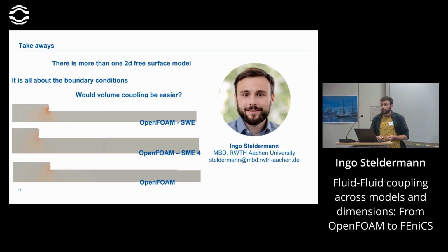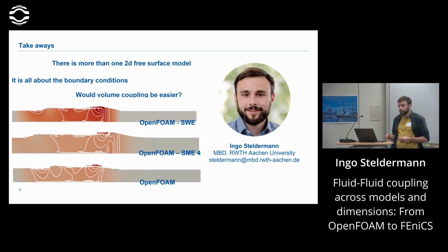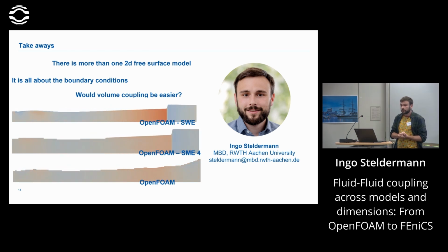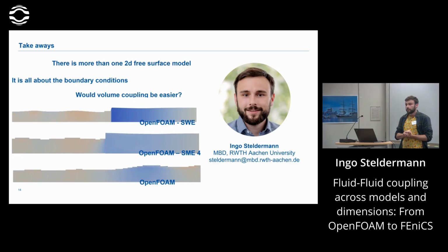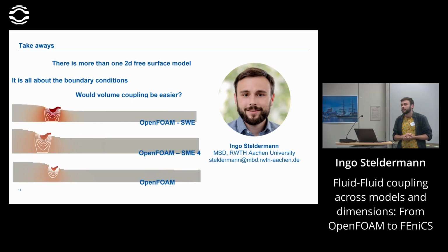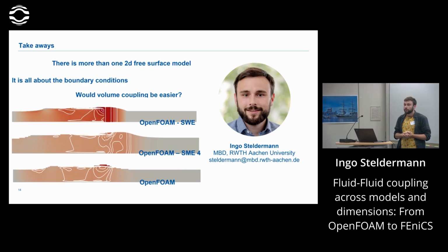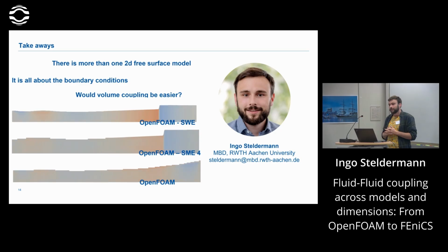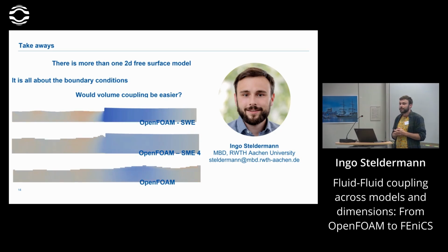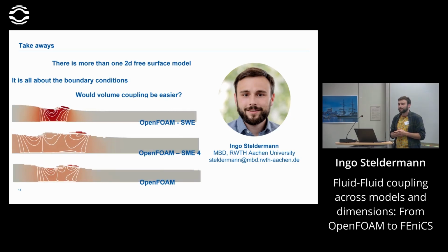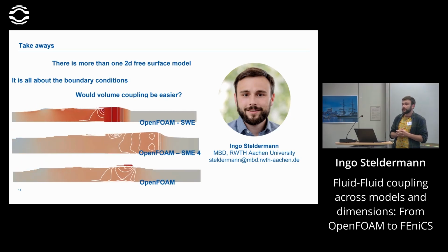Very nice talk, but just to get me right: when you're coupling from the shallow water to the full model, you're just reinterpreting the depth-averaged U as a constant U. Yes, this is the most simple one. This is not the one that people do. You can enrich this data. Immediately on the left of the boundary, you've got the full U profile, including its shape. So you can reinterpret the U bar using the shape on the left of the boundary, and you get much more accurate coupling. Yes.